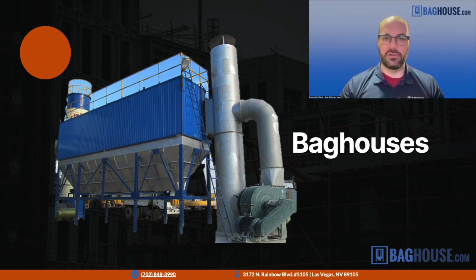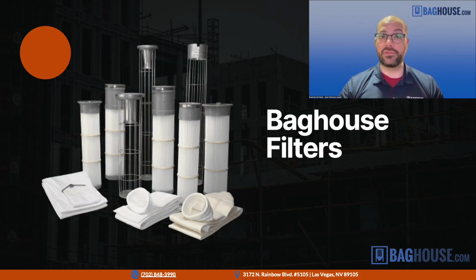Let's see now, a detail here is the type of filters we use in the baghouses. So as I said, we use fabric filters in the shape of bags in the baghouses. The most common materials we make the bags out of are going to be polyester. And then for temperatures that are a little higher, I think dryers, kilns, things like that, we're usually going to see aramid bags or Nomex bags.